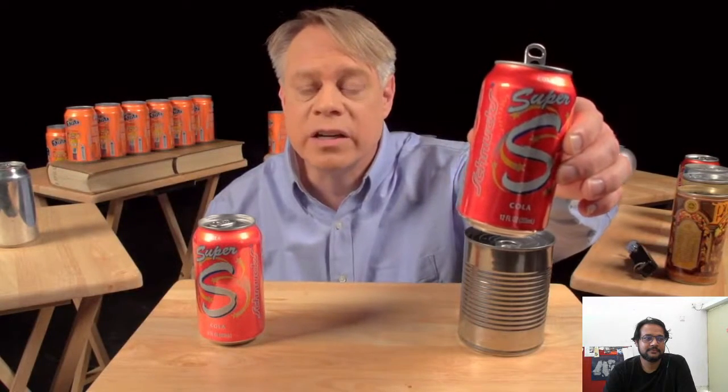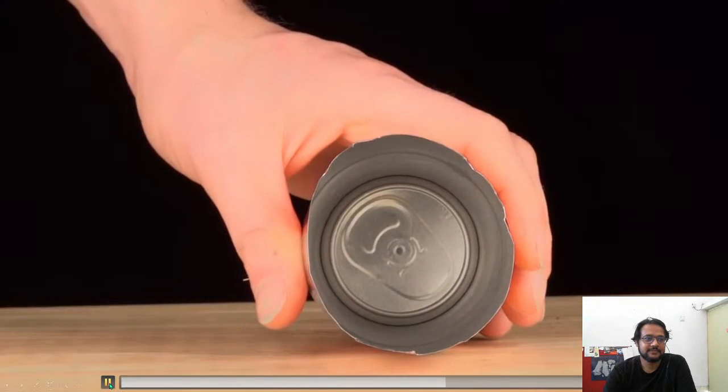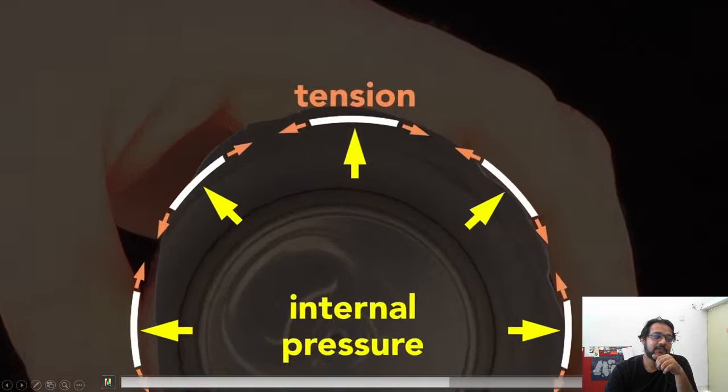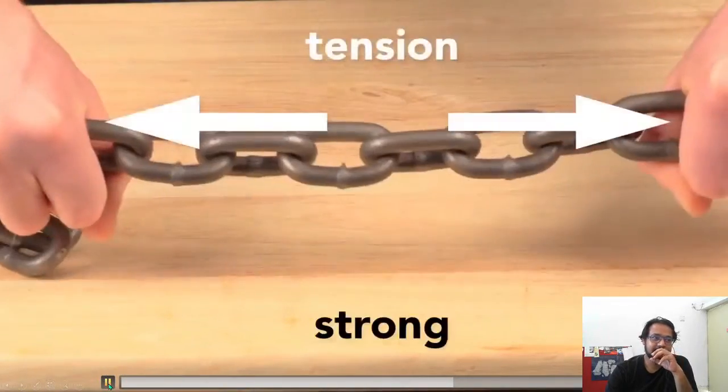Squeeze a closed pressurized can, it barely gives. Then squeeze an empty can. It flexes easily. The can walls are thin, only 75 microns thick, and they are flimsy. But the internal pressure of a sealed can pushes outwards equally and so keeps the wall in tension. This tension is key. The thin wall acts like a chain. In compression, it has no strength, but in tension, it's very strong.